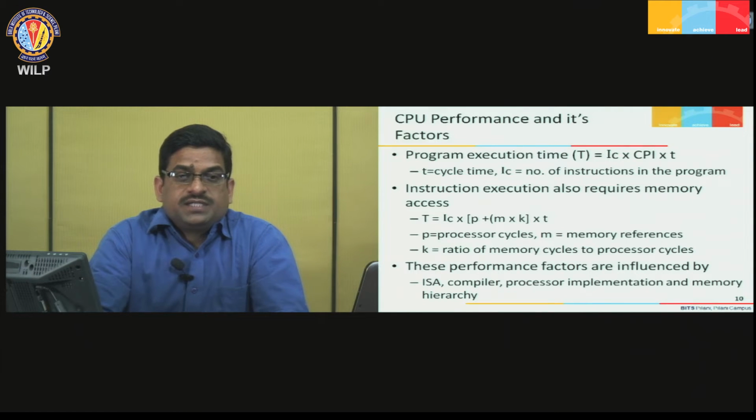The memory is not a single unit in the processor. The lowest level of the memory is your registers, then you have the on-chip cache memory and the off-chip cache memory, then the main memory, and the different levels. Cache has different levels, level 1, level 2, level 3. So, it also depends upon from where the data is fetched, what is the hit ratio of the cache memory, because the access time for the cache memory is less than the main memory access time.